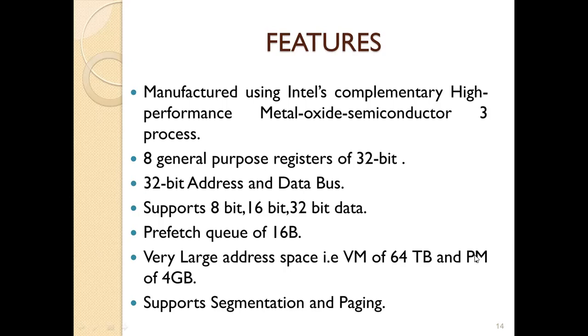It supports virtual memory of 64 TB and physical memory of 4 GB. It supports segmentation and paging. The 80386 supports paging and segmentation. It has 8 general purpose registers of 32-bit. It has a prefetch queue of 16-byte.